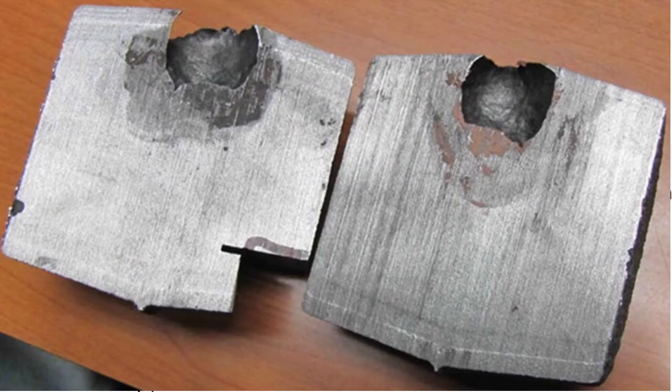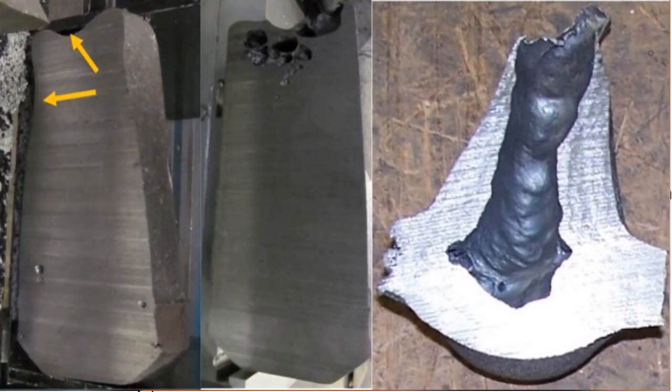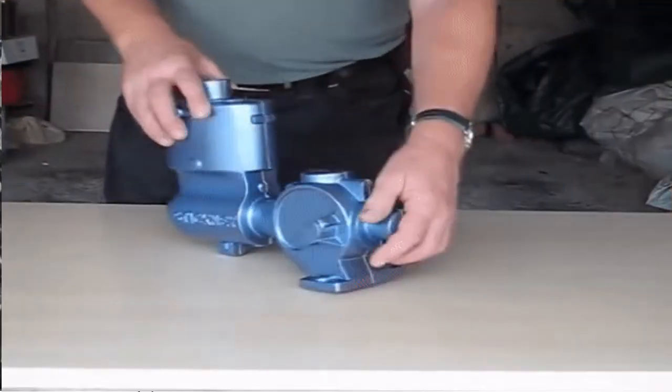The solidification shrinkage occurs in nearly all metals because the solid phase has higher density than the liquid phase. The solidification will cause the reduction in the volume per unit weight of the metal. The only exception we have is cast iron, because it has high carbon content.